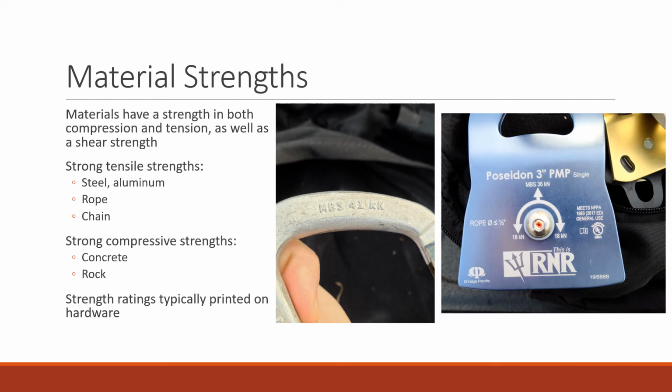Looking at this pulley, you'll see it has a 36 kilonewton strength at the eye, and then 18 kilonewton strength on both edges of the pulley coming off the sheaves. So you can see it has different strengths because it's figured out differently to take load that way.